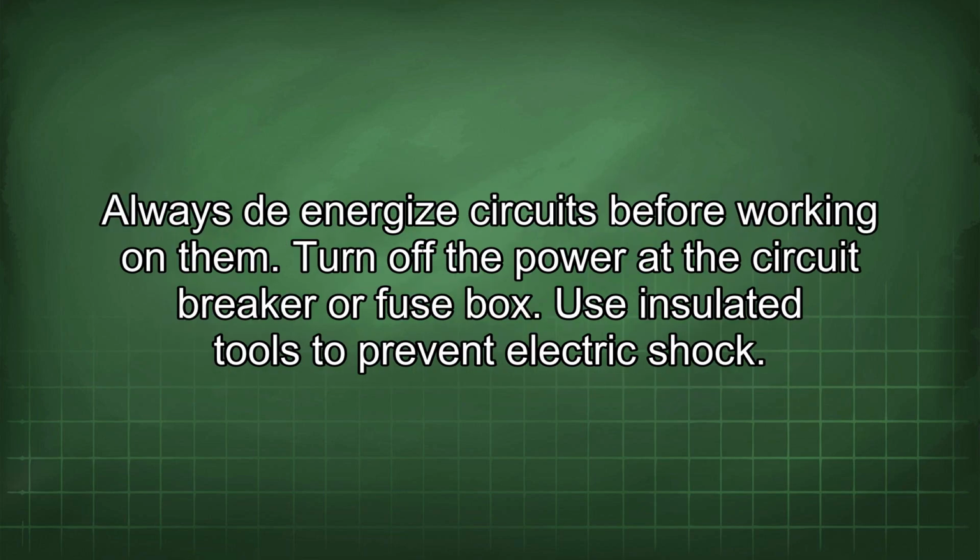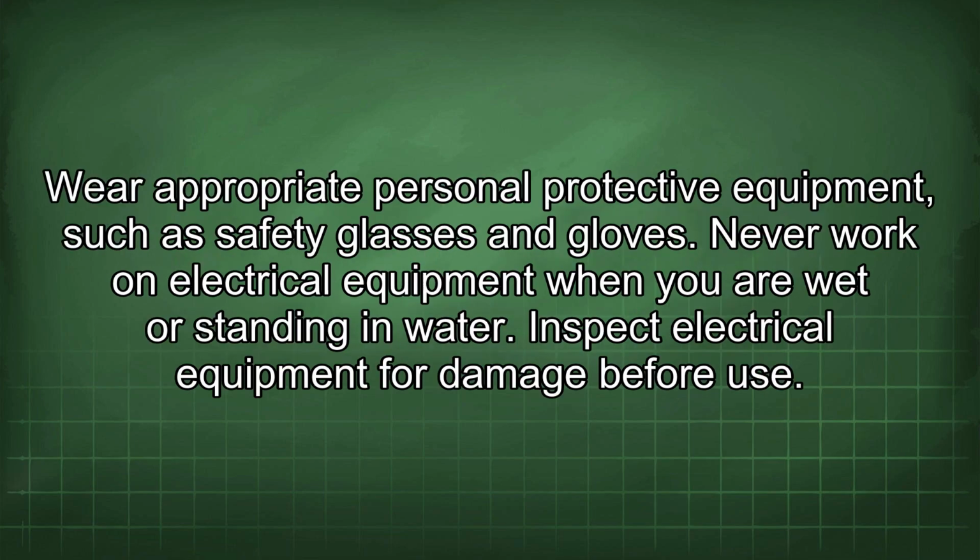Always de-energize circuits before working on them. Turn off the power at the circuit breaker or fuse box. Use insulated tools to prevent electric shock. Wear appropriate personal protective equipment, such as safety glasses and gloves. Never work on electrical equipment when you are wet or standing in water.